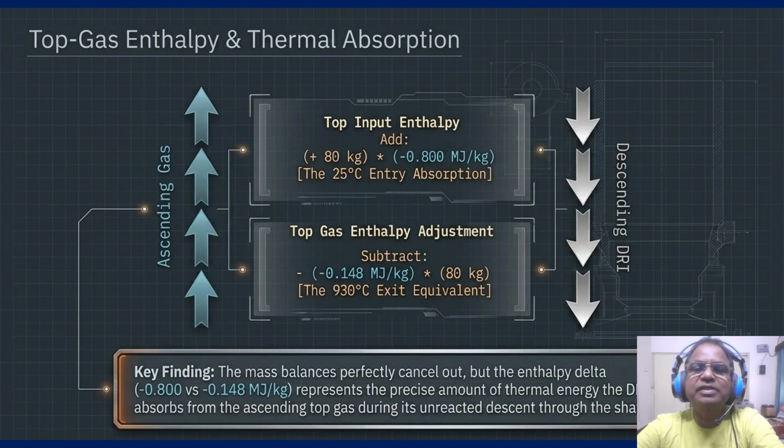With the math settled, let's look at the real-world operational impact, starting with the economics of the feedback. Coming to the data, it is clear and linear. On the left, the coke requirement graph shows a steady decline as DRI input increases, because DRI contains 93% Fe. Very little reduction is needed, and thus minimal coke is required to convert it into molten iron. Similarly, the iron ore requirement drops significantly for every 1000 kilos of Fe produced.